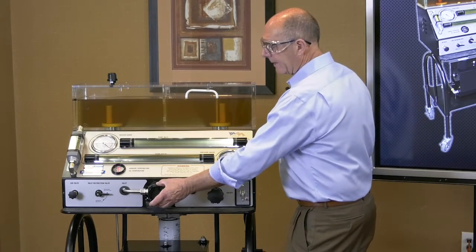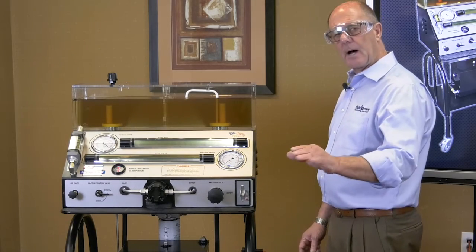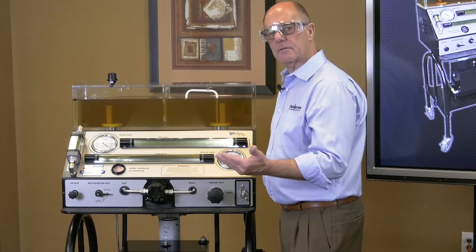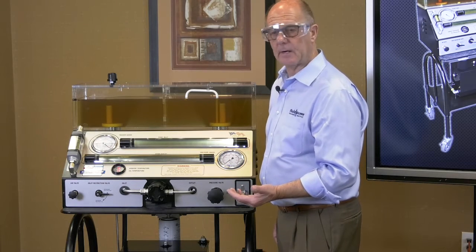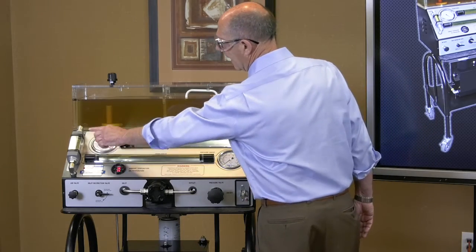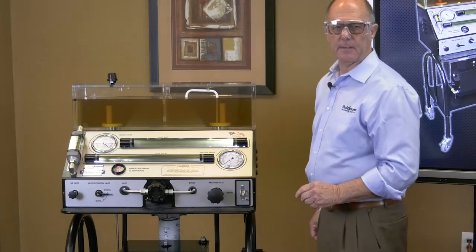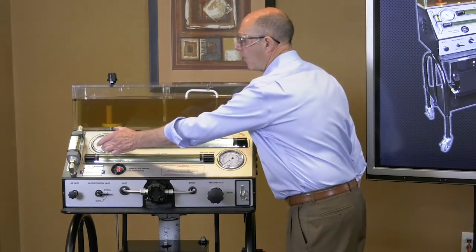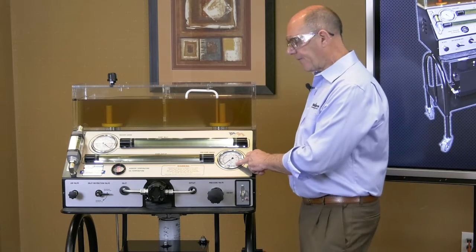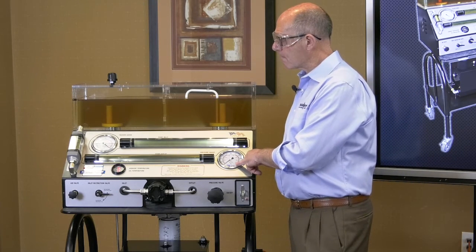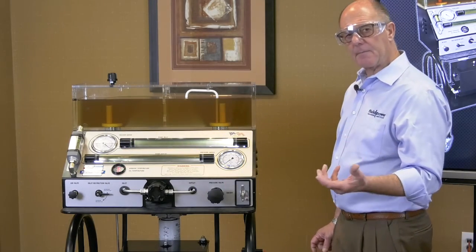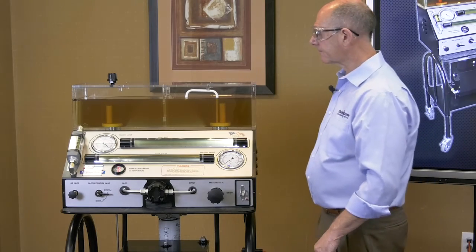I have a 1.8 gallon per minute gear pump, and bear in mind our rule of thumb for inlet restriction on a gear pump is 8 inches of mercury at 135 degrees Fahrenheit, at normal operating temperature. I also have a flow meter, an analog 0 to 2 GPM flow meter. I have a 4-inch 0 to 30 inches of mercury vacuum gauge, and I have a 4-inch pressure gauge. I also have a gauge which shows me both ambient and oil temperature.